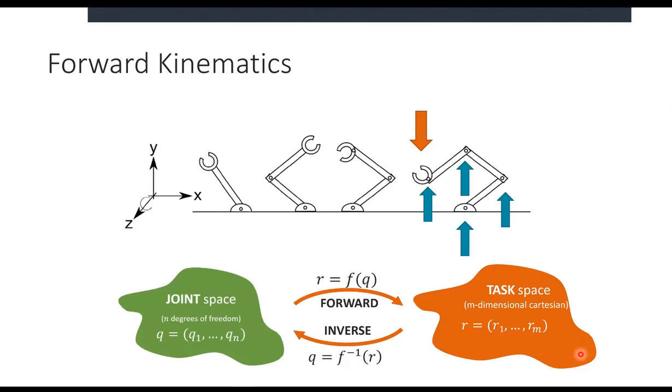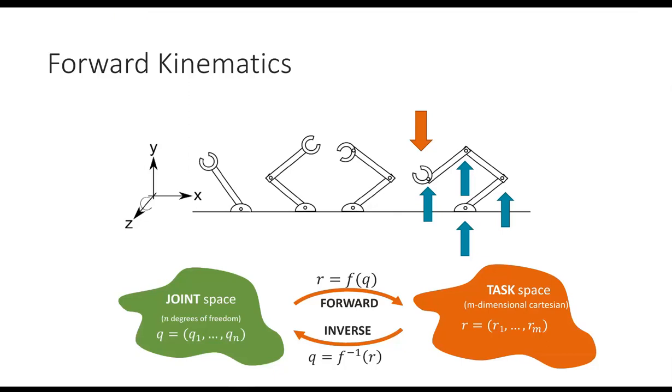And inverse kinematics is just going to be the inverse of that function that is going to take in a particular position and then return for me what configuration of my robot will get me there. And this is a very important concept. This is something that you will carry with you for the rest of the course. So whenever we talk about forward kinematics, you have the joints and you want to know where your robot's going to be. For inverse kinematics, you have where you want it to be. You just need to figure out what the joints are.